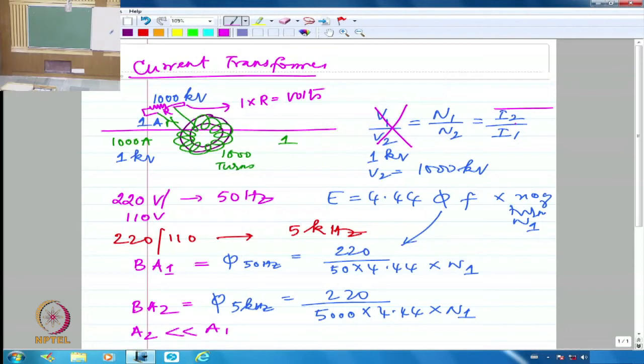That's one reason why if you look at the electronic systems, generators, all those things in aircraft, they will all be operating at 400 hertz generally. They will not be operating at 50 hertz. We are not transmitting it anywhere. It is within the aircraft itself.